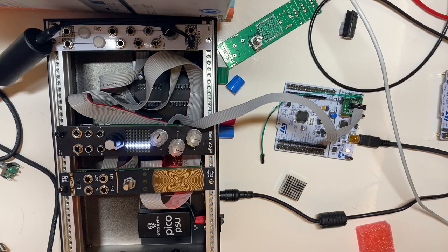The plan is I'm going to do a recap of what I'm going to cover, because we're actually making pretty good progress now. I'm going to do the pots next, so that's reading the knobs, and we're going to use that to animate the display. As a side effect, that will also give us CV input just out of the box, and we can look at that, and we'll use the Analog Discovery scope to generate inputs, send them in to the CV, and just see that the numbers are waggling around, basically.